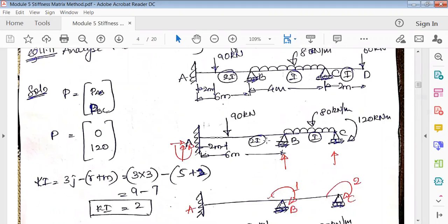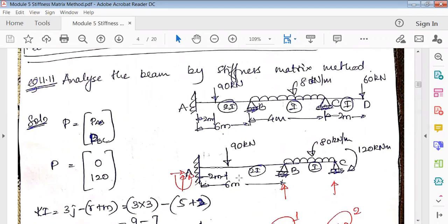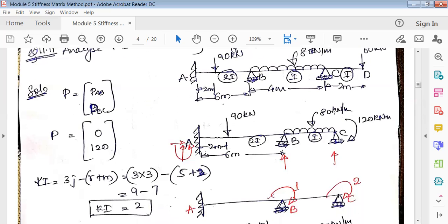Okay, so when you get the overhang problems as such, what you're supposed to do is convert this overhang and show it as a moment here. Okay, so in that case, it would be A, B, C. So instead of the CB, okay, so 60 into 2. So this is going in clockwise direction. So convert this moment into 60 into 2, that is 120, and show it here. Now this is the final form of the figure.